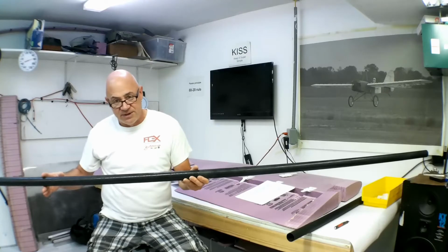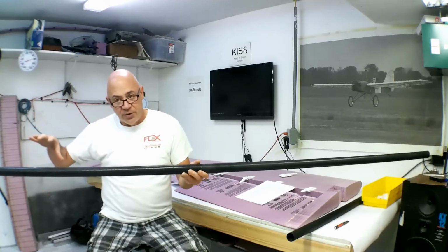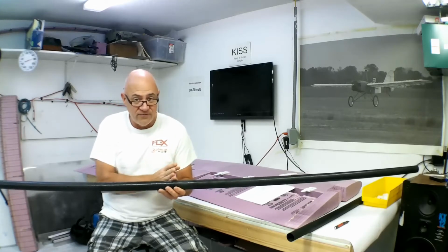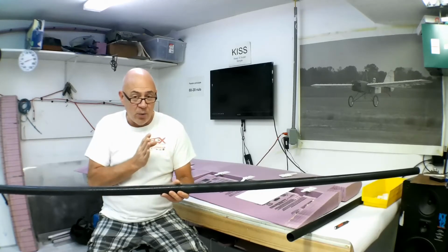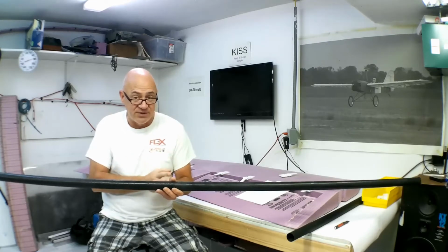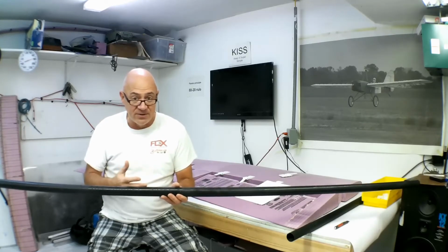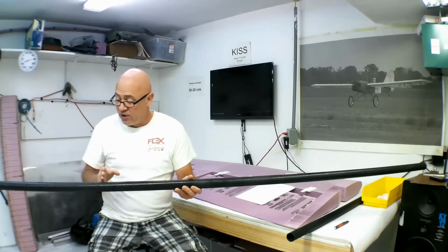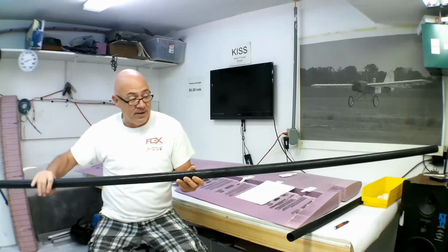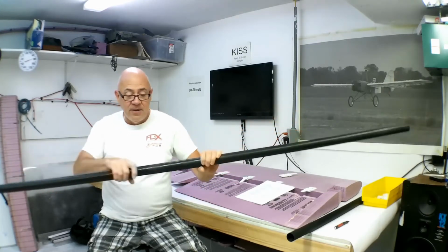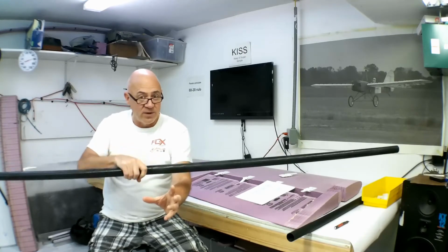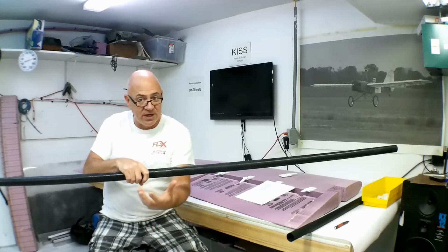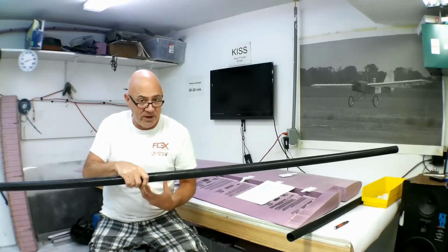But I go out 55, 60% of the wing, and then I take the weight I want to test in G. So if it's a 20-pound fuselage, and I want to put 10 G forces, that fuselage would weigh 10 times. It would weigh 200 pounds. But you have to divide that because you've got two wings. So you come out that 55 or 60%, and you put 100 pounds here, 100 pounds there, and support your fuselage, so the same forces as in the air are on the fuselage. You put a stand on the fuselage. You don't want that fuselage to crush, because you might be supporting it in a weak spot.